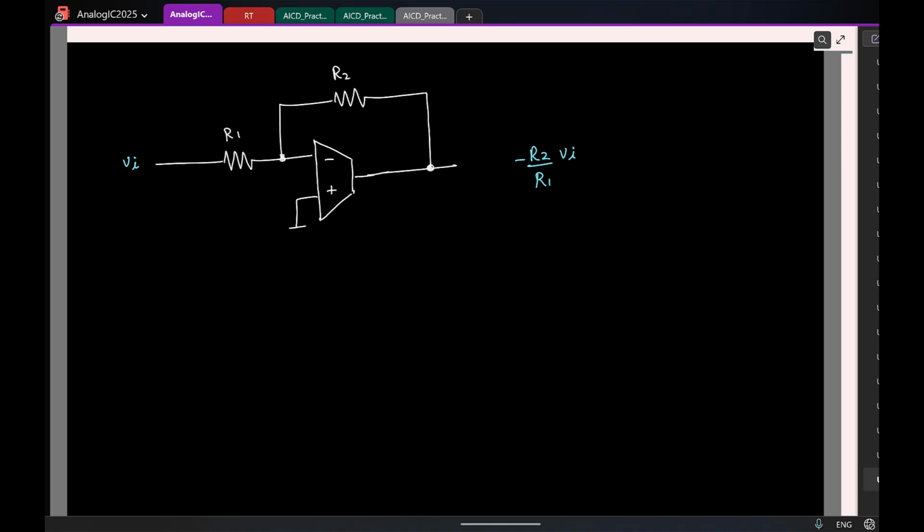Now by this time it should be clear that I can't actually connect this to ground, 0 volt, because this is going to the gate of a transistor. So this is just a small signal ground. So in practice, where will I connect this to? Some DC voltage source. I'll call it some bias voltage VB. Similarly, the small signal voltage should also not be given directly. I'll use some other bias voltage. I'll use the same voltage for simplicity. So which means even at the output side, I will have some bias voltage plus the small signal part. Correct?